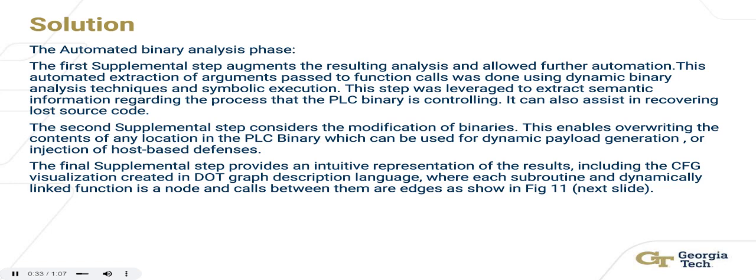The second supplemental step considers the modification of binaries. This enables overriding the contents of any location in the PLC binary, which can be used for dynamic payload generation or injection of host-based defenses.